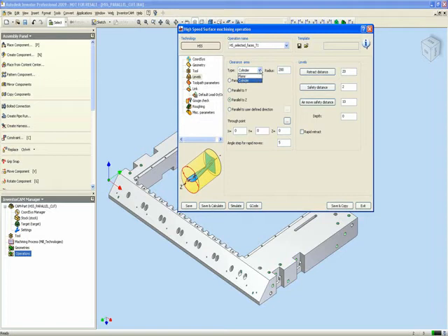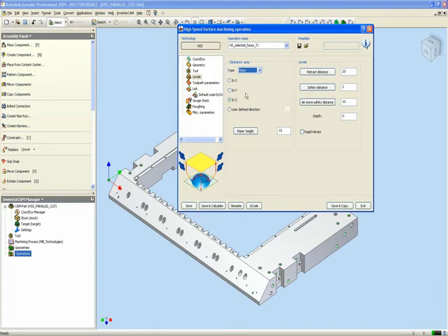In this particular case, I'm going to choose the option of plane, and we have the choice of retracting to a clearance area either in X, Y, or Z. In X, Y, or Z, for simple reasons, sometimes we're working on the side of the part with an undercut, and we first want to retract in the X or Y direction. In this particular case, I'm going to choose the Z direction, and over here we have the plane height as to where to retract to.